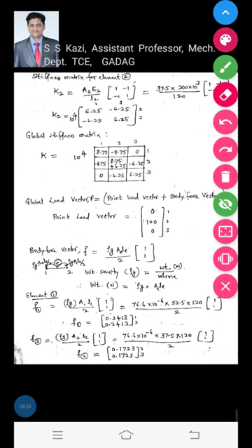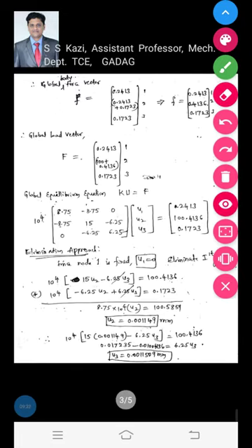Now next, similarly you calculate the body force vector for element 2: rho g A2 L2 by 2. Rho g, that weight density, is the same as it is the same material. Next, the area is 37.5 mm square, 120 is the length, into 1 1. By calculating this ratio, we got 0.1723, and you write the DOF numbers 2 3, because element 2 consists of two nodes, 2 to 3. Now next we will proceed to the next page.